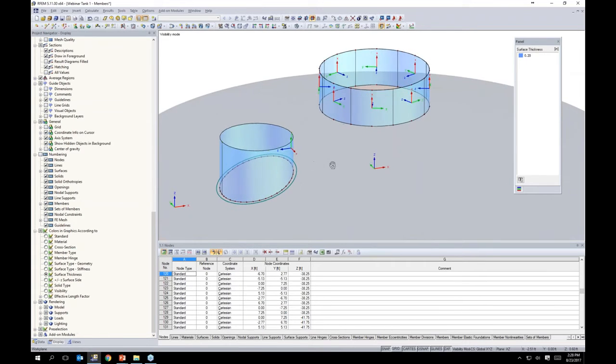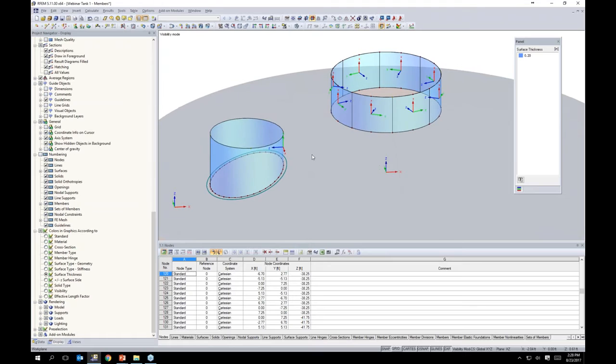So now that z axis is facing inward, but something else to discuss. Not only for loading purposes, but for our results, local axes are very, very important. Our results are going to be presented to us in terms of surfaces' local axes, such as forces in the local x direction, forces in the local y direction, stresses, and so forth.